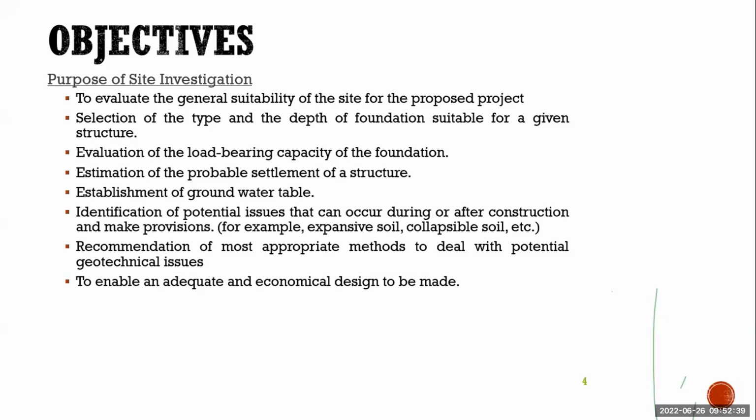Then, are there any potential issues? Like, if the site has expansive clay, you have to take proper precautionary measures after the construction. Of course, you have to replace the soil, but at the same time, around the foundation also, we have to make sure it is not going to affect the foundation in future. So we have to see how the site can affect the project during and after construction, and future construction. Then we will know what the potential geotechnical issues are.